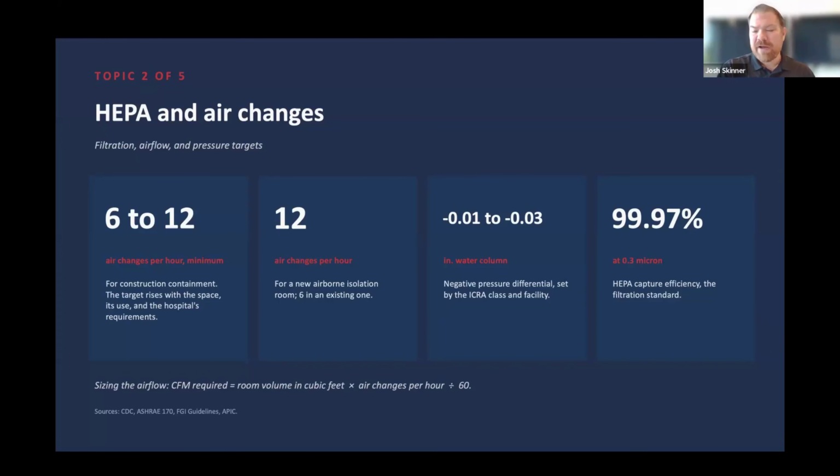Piece two is, are we overflowing the machine? So we've been on sites and seen the horror stories of people that forgot to put the HEPA in the machine in the first place and then been feeding out into the hospital. That's the worst case scenario. But on the flip side of that, you have contractors trying to be too efficient. They're putting in the wrong filters or too many pre-filters before there, and they're actually clogging up airflow, all with the best intention of, great, more filters means cleaner air, better efficiency, but they're actually preventing airflow and CFM in the first place. So if all of those are done right, if you're using the recommended pre-filters, you've got the right HEPA in there, then how do you know?